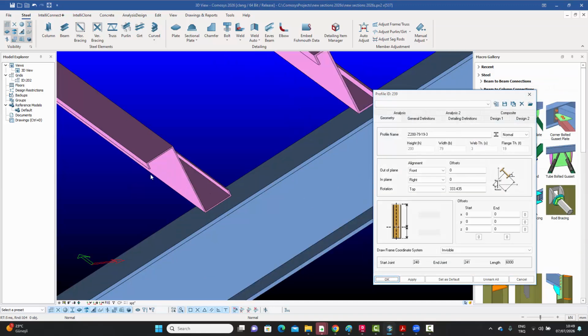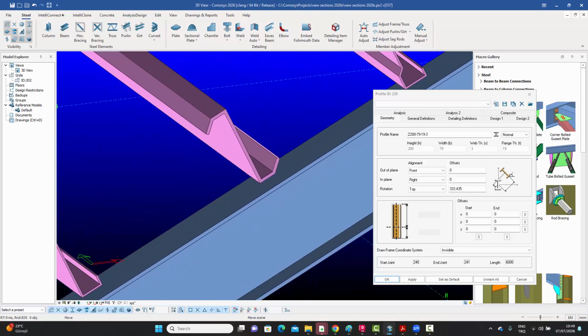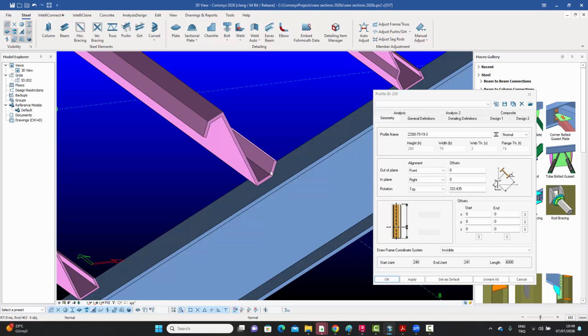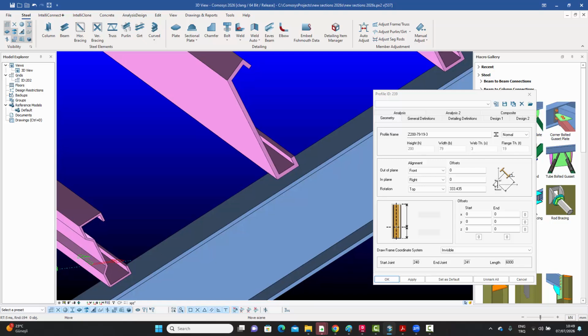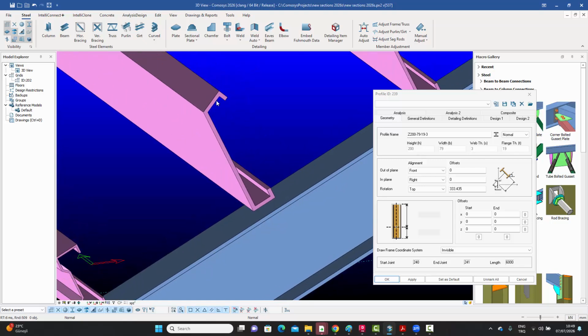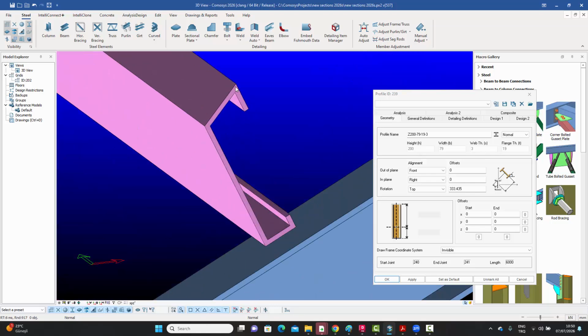So we already had the Z profile, of course. This one was there, the unsymmetrical Z with this flange width different from this one. Now we have this, where the lip is at an angle over here. The sigma cold formed is there. Then we have now added this one with the top flange sloped and the lip perpendicular to that slope, like that. And then there is another one in which the same slope exists, but the lip is actually vertical or aligned with the bottom lip.